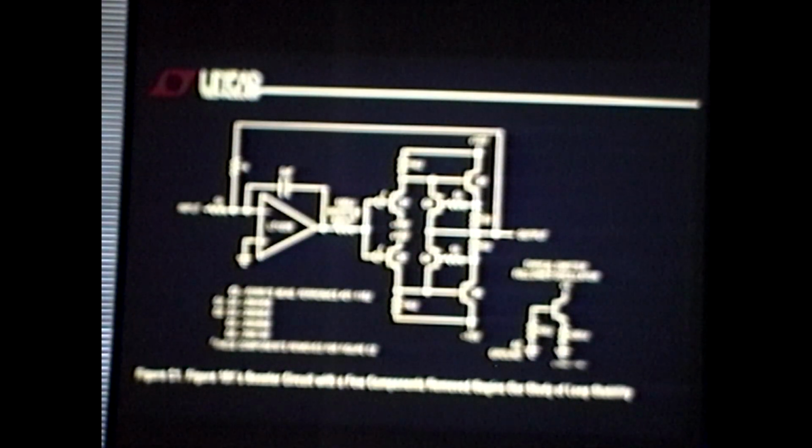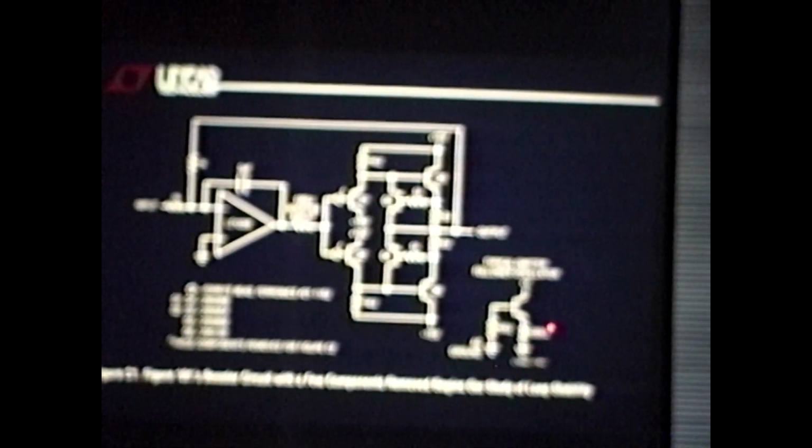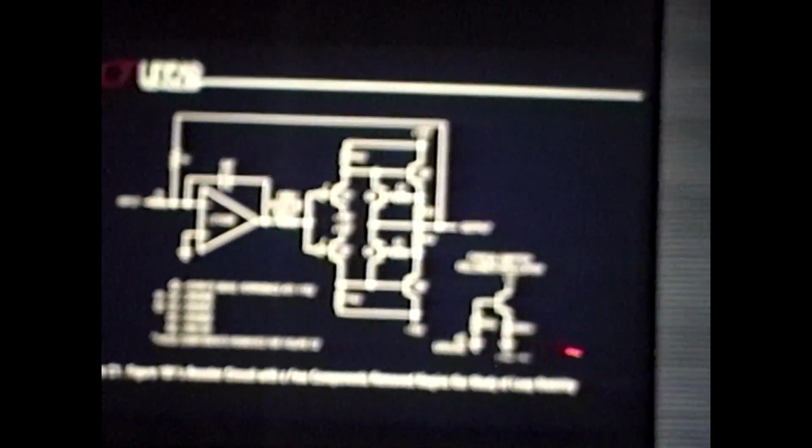Typically, when people do things like this, the phone call you get is, it oscillates. Okay? There are questions to ask when the customer says it oscillates. Remember, I said there were 2 kinds of oscillations in a situation like this. One is something within the booster is oscillating. That is to say, it's not a feedback loop phenomenon. There's something in here oscillating. And I said emitter followers can oscillate, particularly emitter followers driven from low impedance sources. This is a typical emitter follower oscillator down here.